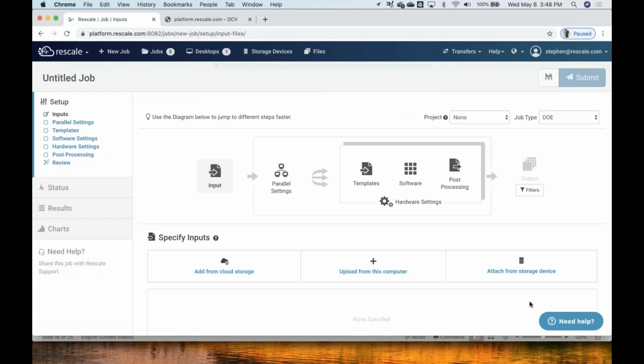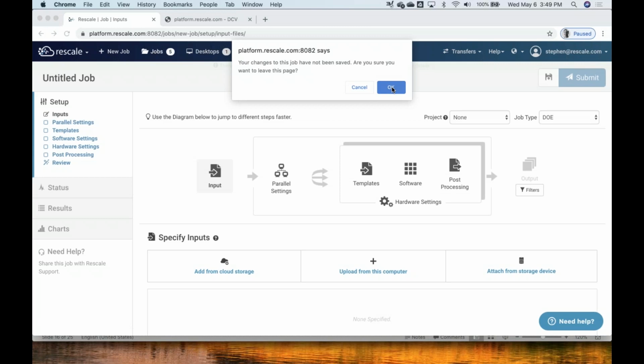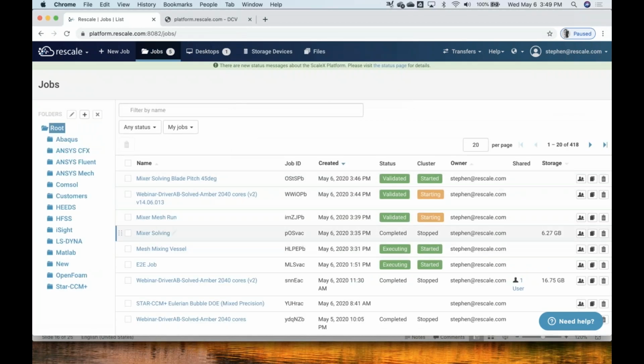As you can see here, this adds another layer that the platform has in terms of managing. Now that we have this fully pipelinable STAR-CCM+ job, we have the ability to change the simulation and the parameters at will, in terms of meshing and running, all of that. Now I can start adding more complexity and look at design of experiments or parameter sweeps, what have you. I already have one set up.